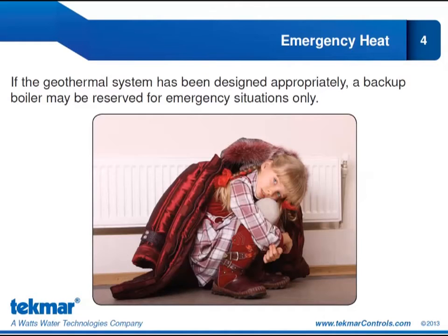There is a setting in the House Control 406 for the backup delay, and we can set that backup delay to a setting called override. In that override setting, the backup only comes on if the heat pump is locked out or offline. So we can certainly program the House Control 406 to respect the emergency heat situation and not to operate that backup heat source unless we truly are not getting any heat from our heat pump.